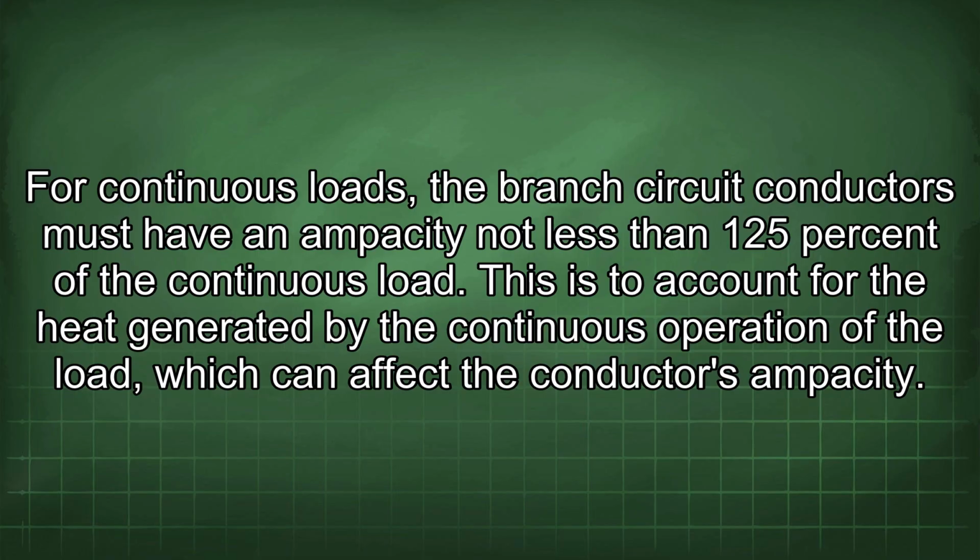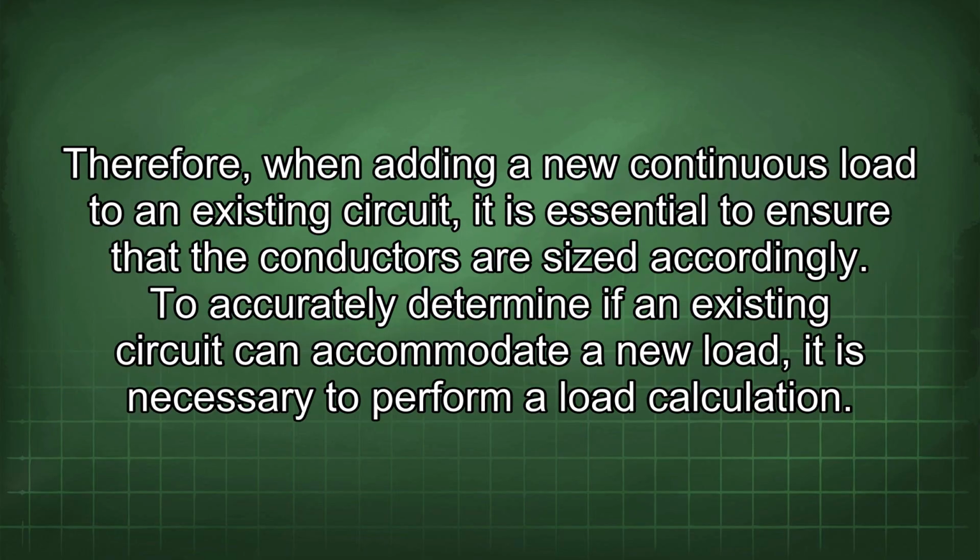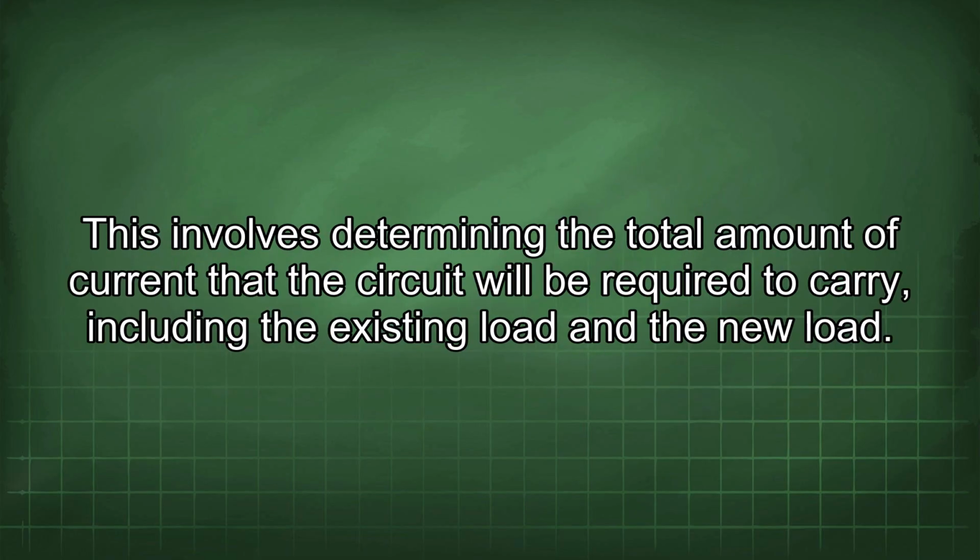This is to account for the heat generated by the continuous operation of the load, which can affect the conductor's ampacity. Therefore, when adding a new continuous load to an existing circuit, it is essential to ensure that the conductors are sized accordingly. To accurately determine if an existing circuit can accommodate a new load, it is necessary to perform a load calculation. This involves determining the total amount of current that the circuit will be required to carry, including the existing load and the new load.